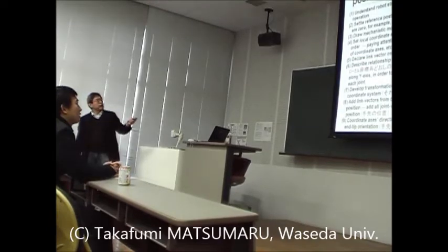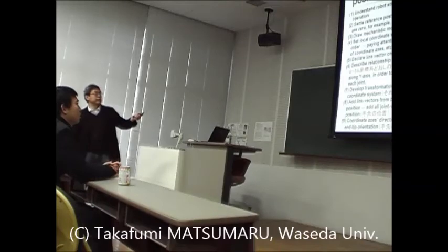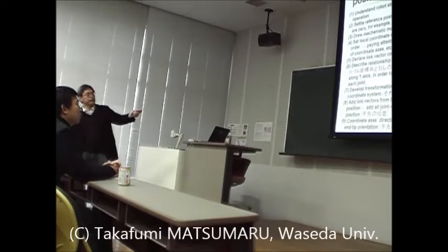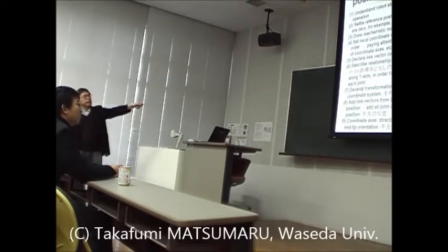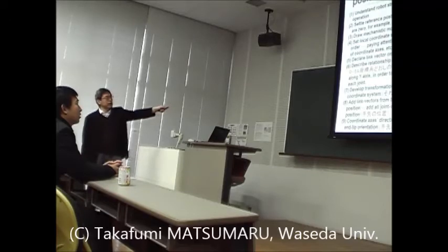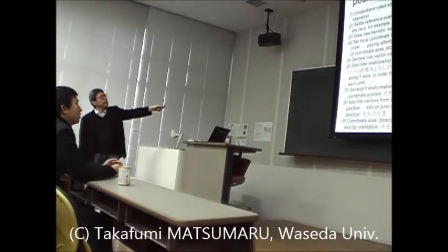Okay? And secondly, set the reference posture. This is the first posture, basic posture, or reference posture. The reference posture means the posture appearance when all joint values are 0. For example, all links and joints are aligned on a line. When all the joint parameters become 0, it is the reference posture, the basic posture. And then draw the mechanical model, a link-joint model, using symbols.